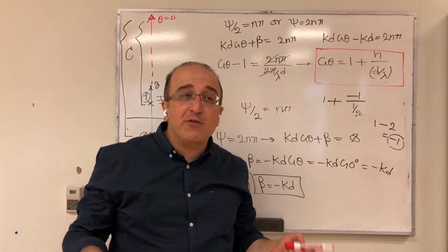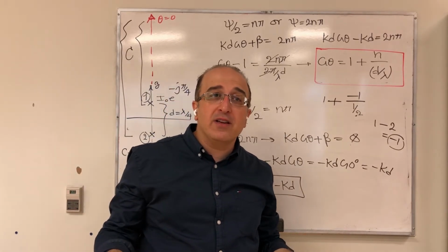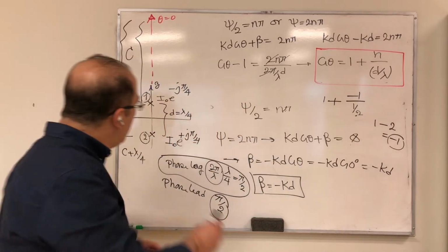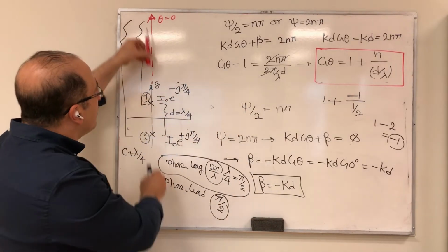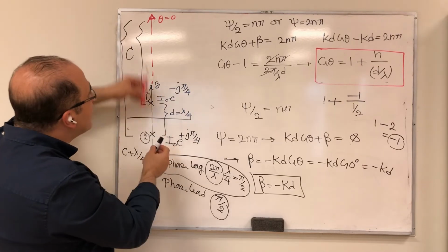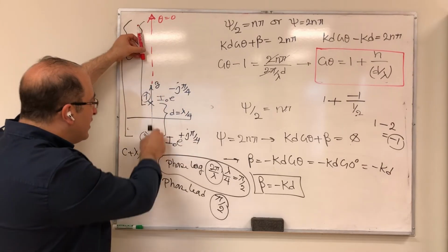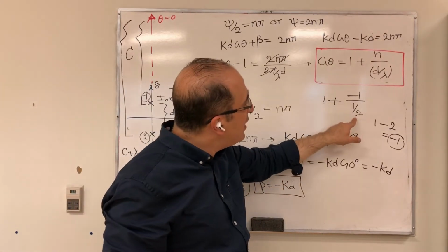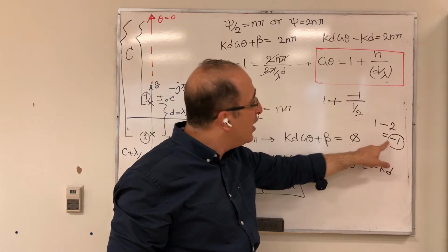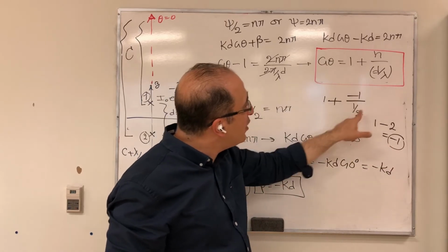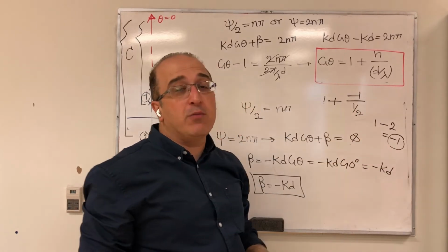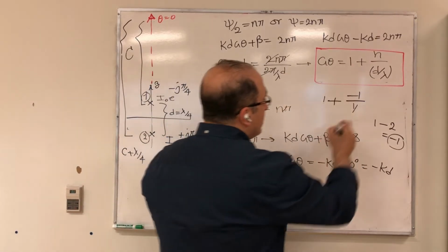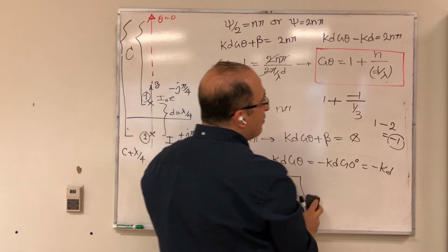Although theta equal 180 is part of the endfire definition, if you want theta equal 180, you usually desire to only have theta 180, not both of them at the same time. So for this case, theta equals 0 is the main beam. This is the grating lobe if it happens. So you see, d divided by lambda gets you to the limit. But if d divided by lambda becomes smaller than 1 divided by 2, let's make an example. Let's say 1 divided by 3. Then it becomes 1 minus 3.